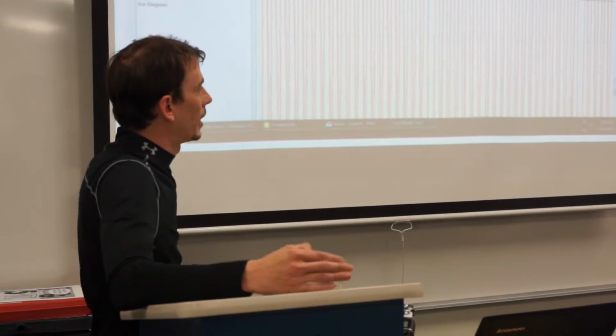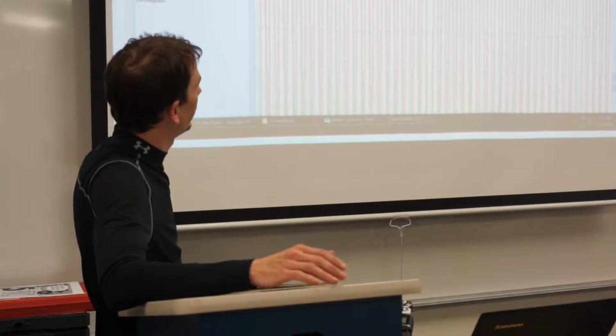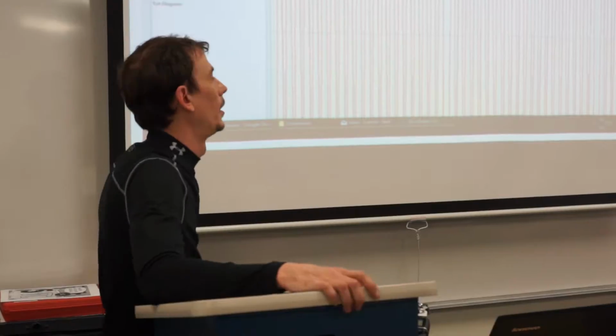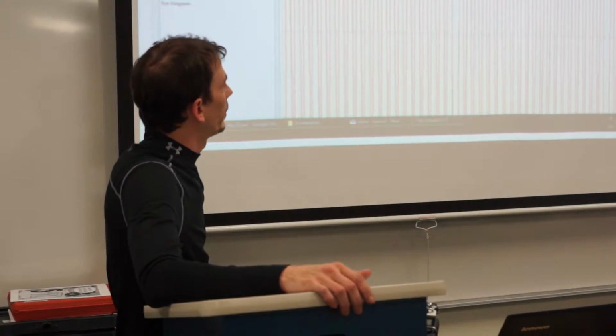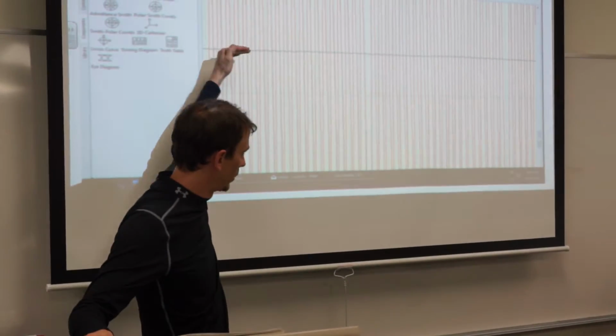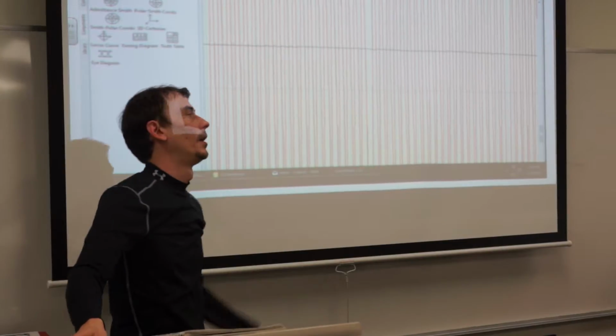The consequence and the compromise that had to be made as well is that, as it turns out in this circuit, when you're increasing the value of the resistor, it starts to smooth the voltage off because the larger resistor slows down the current, and it's not going to change as fast between our pulses.